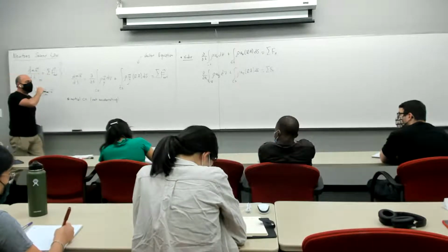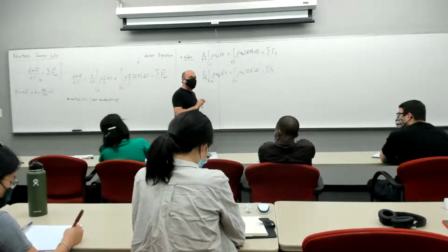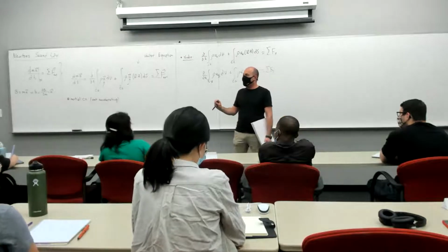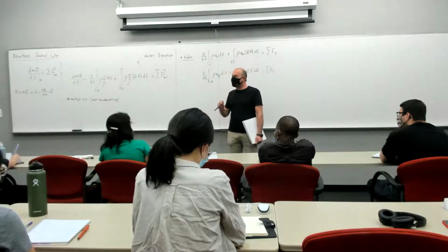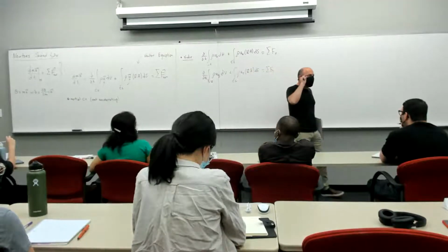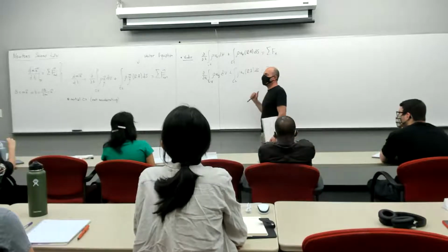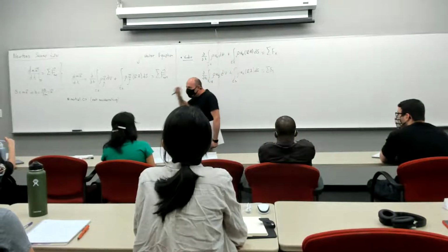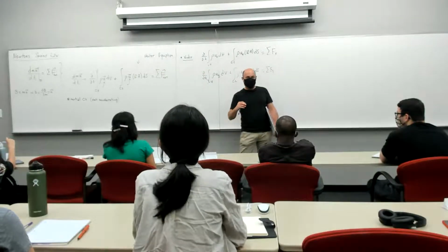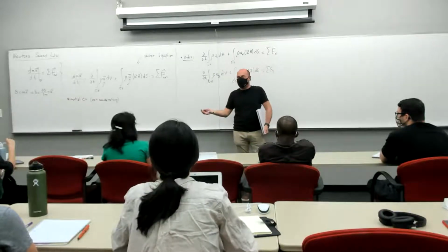Now, the summation of the external forces, you might think that they're going to be different for the system than they are for the control volume. Well, they are not. Because the way we derive the Reynolds transport theorem, we said it's at the instant when the system coincides with our arbitrary control volume. And at that instant, the forces are going to be identical, the external forces. Okay? Because they're acting externally on the system or the control volume, it doesn't matter.